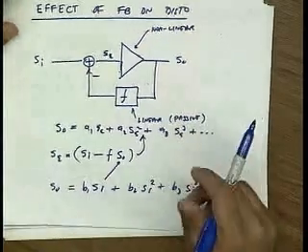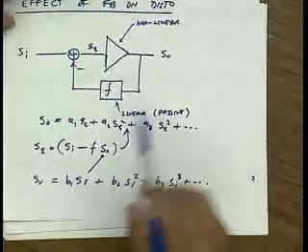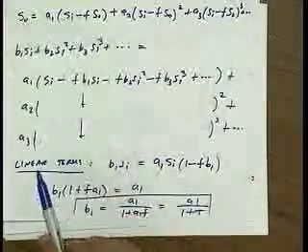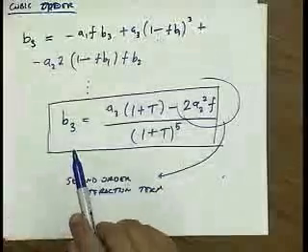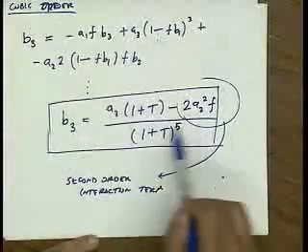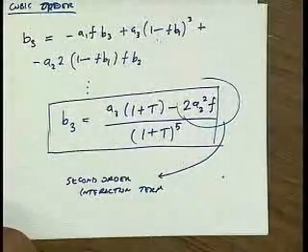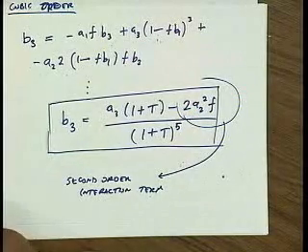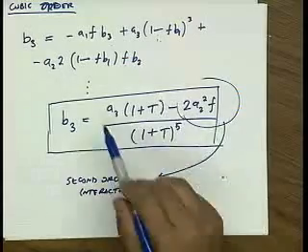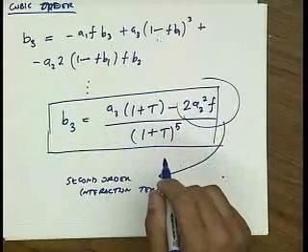Now the good news is that maybe I can use this to actually cancel out my third order, right? After all, there is a minus sign here. So maybe if I'm careful, I can use second order interaction to cancel out my cubic. Turns out that, yeah, you can do this, but it's very sensitive to process parameters, as we'll see for a practical example.